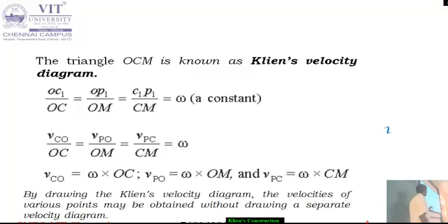This you know. So this is the acceleration diagram for this 4-bar mechanism. As usual we use the procedure of radial component and tangential component. Okay. Now what I am doing, I know the value CM. I extended it. So take CM as radius and draw one circle. So one circle is drawn there. Okay. So this is the way you can get the acceleration diagram without drawing the acceleration polygon. And take PC, that is the connecting rod, as the diameter and draw one more circle. You know the connecting rod length, take the midpoint and from that midpoint draw one more circle.